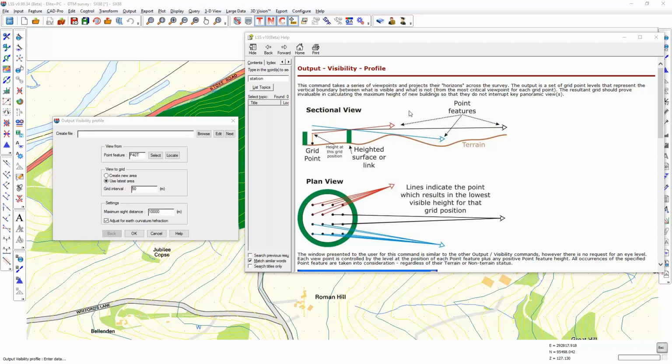You also decide where your critical receptor locations are going to be, and LSS will then attempt to draw a line from each of the receptors in turn to a user-defined grid of points within the development area. And what it will store is the lowest altitude from all of the receptor locations below which none of the development will be visible.